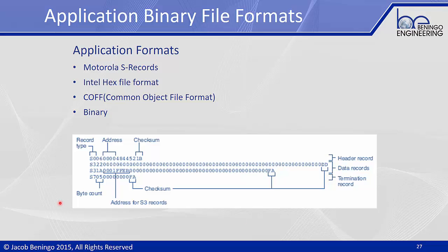We may find that we want to tell the bootloader how many records to expect, and maybe we want to provide a record number for each of the different records that we're going to send down, in addition to any command and performing additional checksumming. So just a couple of ideas on how we can go about creating an even more robust bootloader.